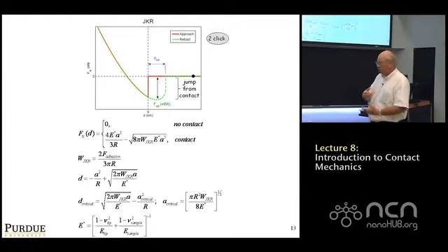When you withdraw, right, the withdrawal curve is described by the green line. And there's a hysteretic behavior, and the green line shows that the tip actually sticks to the substrate until it finally jumps from contact. Okay? So the model is a lot more complicated. It involves a lot more parameters. There's an implicit relationship between the contact radius A and the separation D, right?